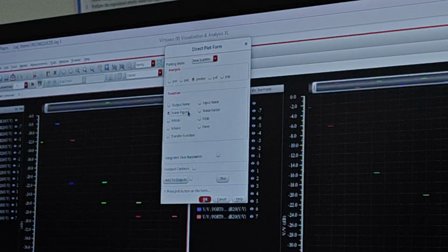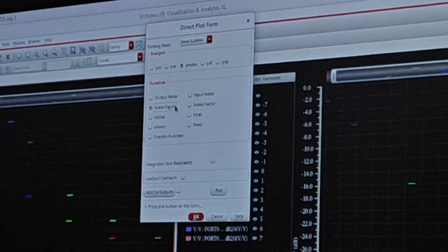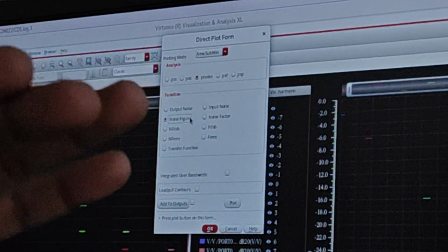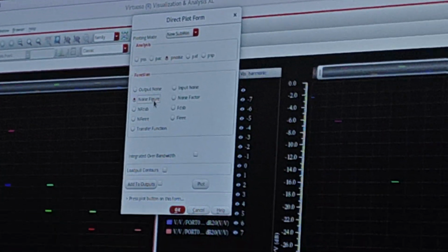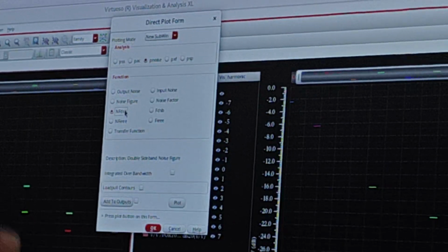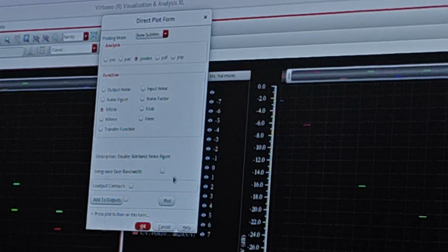When you are doing IF down conversion, it will be completely in the positive frequencies, or wherever you want to see. So this noise figure is a single sideband noise, where you see the spectrum completely on one side. NFDSB is like a two-sided spectrum, so it will be like half of the noise. If you see, we'll understand.